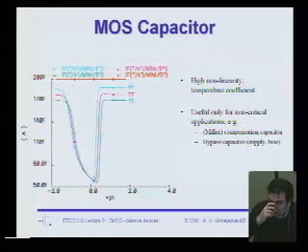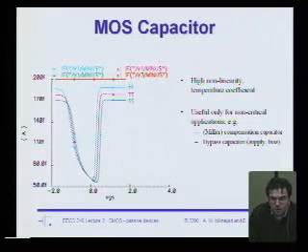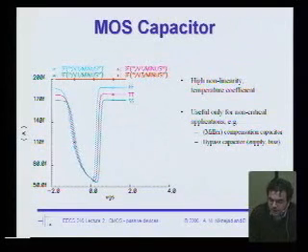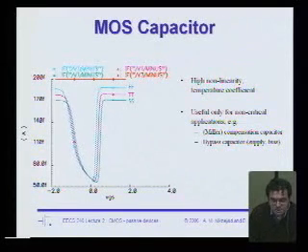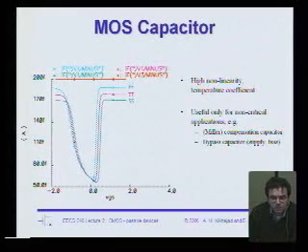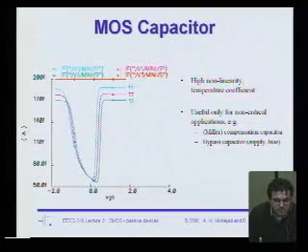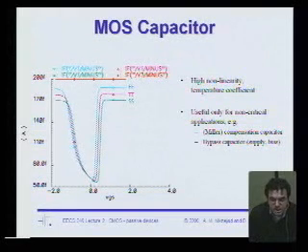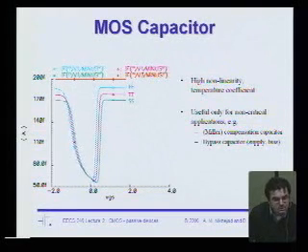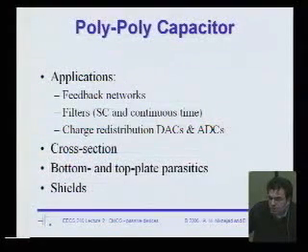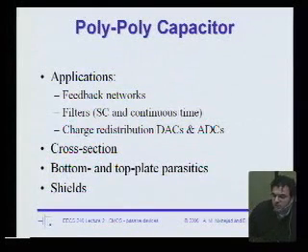So one of the first things you should think about in this course, you probably haven't thought of before, is anytime you do a design, don't just simulate it at typical corner. Simulate it at slow, simulate it fast, simulate it at hot, simulate it at cold. Change the temperature, change the process. PVT, process and temperature variations. Okay, polycapacitors we already talked about.